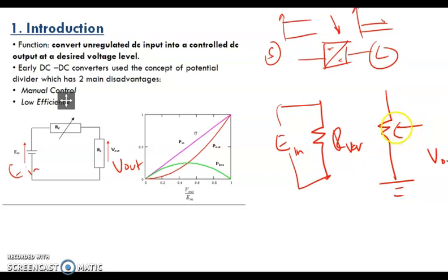If you shift the voltage probe higher, V out will be higher. If you shift it lower, V out will be lower. So it's just like the voltage divider rule. You probe the output here, shift upper or lower, and V out varies based on the resistance that appears at the probe.